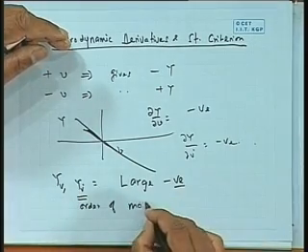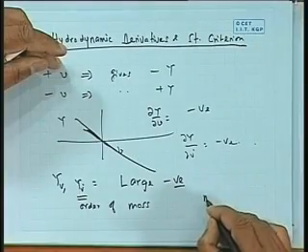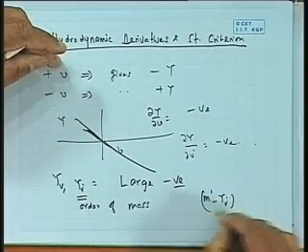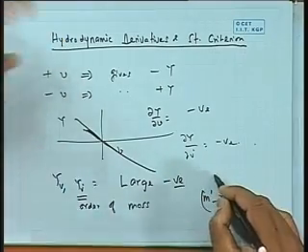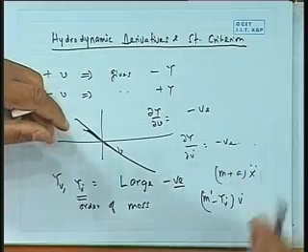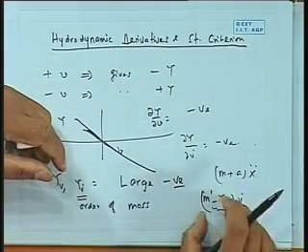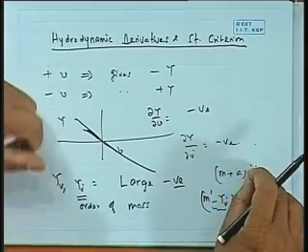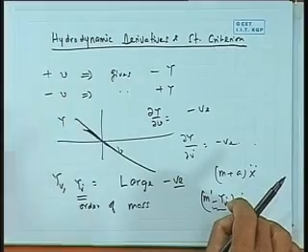In fact, this is of the order of mass, because it is the added sway moment of inertia. In fact, the equation is written m dash minus Yv dot v dot. It is interesting because in our other equation, it was mass plus added mass into acceleration. So this has become the added mass. Minus Yv dot is added mass, not Yv dot. See, Yv dot is negative, so minus Yv dot becomes added mass.